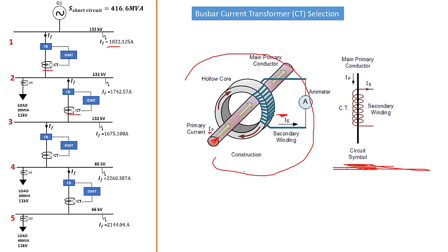So you just have to work in terms of the ratio. This one is going to be a small one. The number of turns here will determine how much you get here. That's where our turns ratio comes into the equations. So for example, for a 1000 to 5 rating, that means you have 1000 on the primary and 5 amps rating, or 200 to 1.